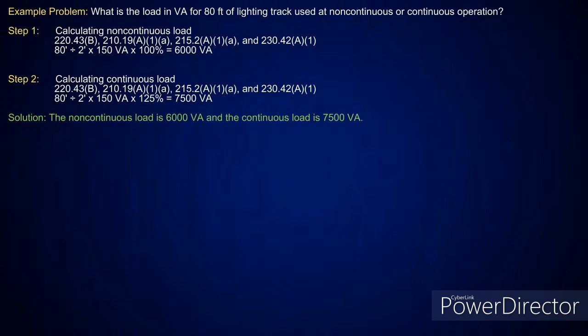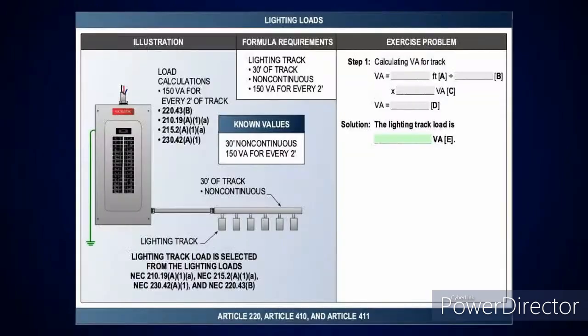Now, I had an interesting question come up about that. Where are your show window lighting receptacles required to be located, on the inside of the tenant finish or on the outside? Well, they're on the inside. That's kind of what I thought, but the code doesn't really tell you. It couldn't be on the outside. That's where your lighting is.